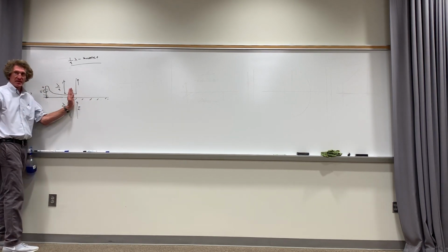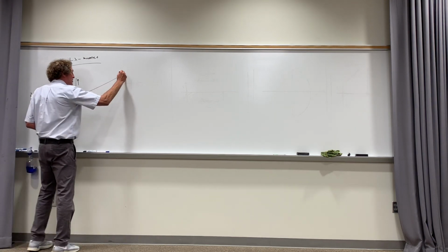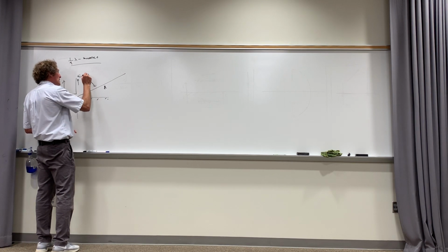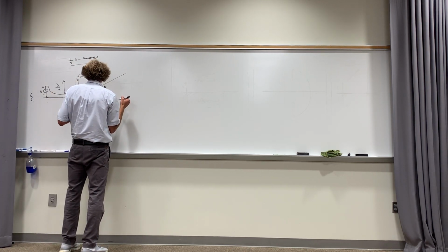So this effectively is the same as a half wave dipole in terms of how the radiated fields will be calculated. If we go a distance r away, at an angle theta, we get the exact same fields we'd get from a full half-wave dipole.